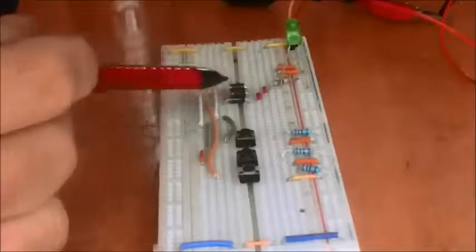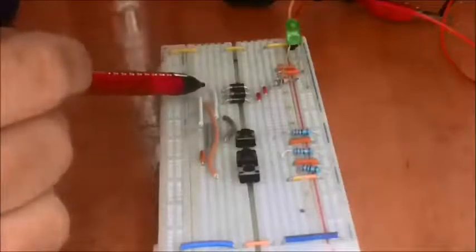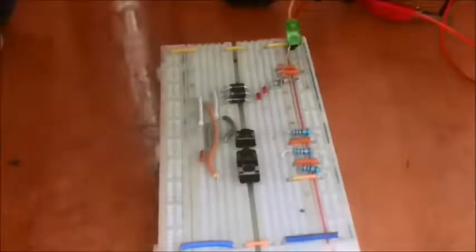One of the big problems with this is that you can't construct a NOT gate. You really can't. And if you want a NOT gate out of it, all you've got to do is stick a transistor in there. Now this sort of thing is called diode logic, or because we've got resistors in, diode resistor logic. And if we stuck a transistor in there, we'd be getting into diode transistor logic. Diode transistor logic is not usually worth it in the long run, as there is a thing called transistor logic, and that's what we'll be looking at with our next example.